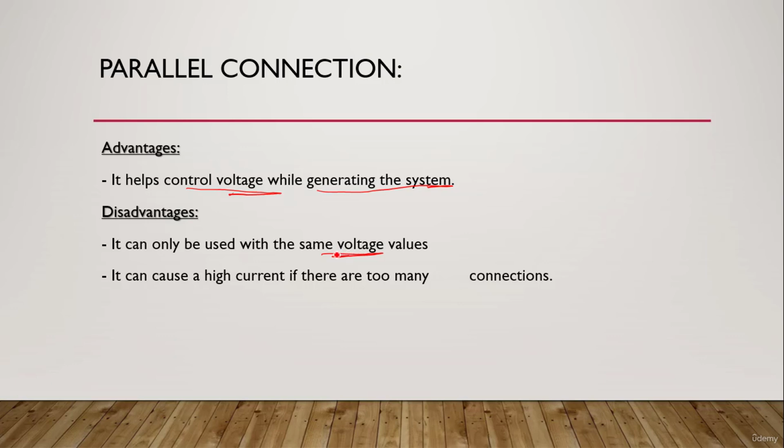If you have multiple PV modules connected together in parallel, all of them must have the same voltage to be connected in parallel. If they have different voltages, the output voltage is going to get the lowest value, as we're gonna describe in the next example.